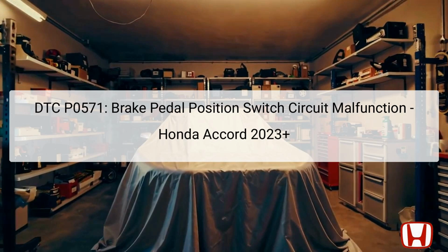The brake pedal position switch is an integral component located on the brake pedal assembly and is responsible for signaling to the PCM about the braking status. Another significant factor in this diagnostic trouble code is that pressing the accelerator while lightly braking for 5 minutes can also lead to the DTC being stored. It is vital to understand this code, as it may affect vehicle safety and operation significantly.